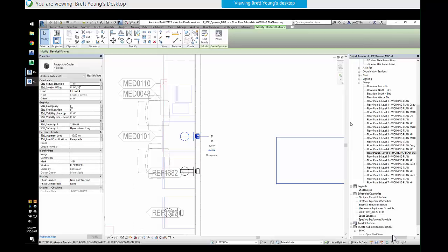So does the design and the way the family is actually built help with placing that initial device on the insertion point? It would. I think if you have to come back and you hit space bar, if it was at, say, the back of the equipment and already near the wall, right, you just select and go flying through it. I'm not sure if I can ask the medical equipment people to make the family base point in the right place. I would love to do that, but one thing I would like to know is which way the medical equipment is facing, and I think Dynamo can do that as well.